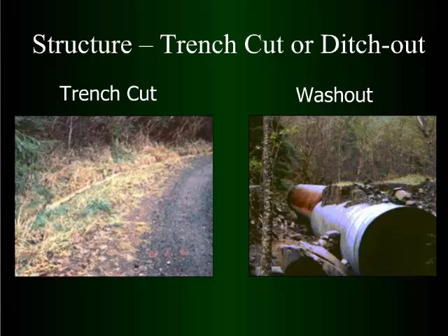One thing you want to be careful with on these is if you've got a road coming down, say a 10% grade, the temptation is once you get off the road to cut these down the hill pretty steep, and you accelerate the velocity, and what you do is you end up with a pretty severe cutting right where it dumps off. So it's important to maintain your ditch outs at a fairly low gradient until it takes it far enough to disperse the water.